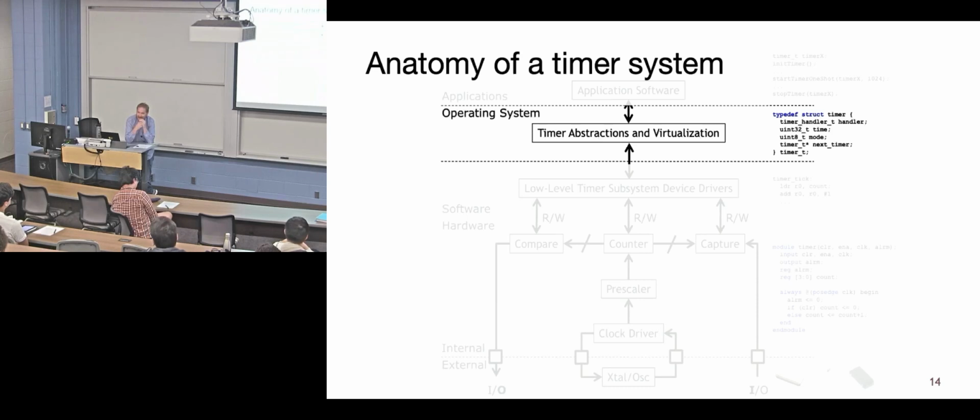Yeah. You run into the same issue where you run out of space on hardware to keep track of the virtual. Right, so in that sense, you could have one timer for each long-term event you want to do. And then whenever that timer goes off, you increment something in the software to keep track of how many times that timer's gone off. But then you're still limited to how many hardware timers you have on chip. Okay, what's the way to overcome that?